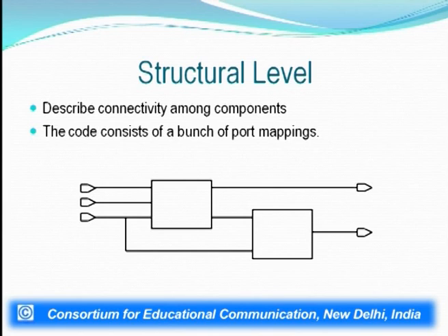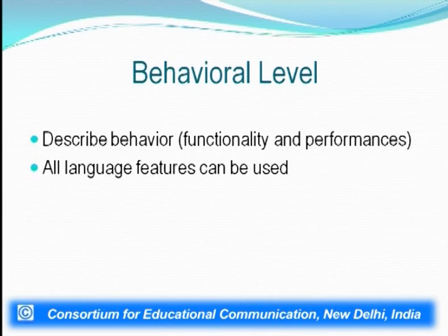For example, talking about a simple full adder, a full adder comprises XOR gates and some AND gates. So a structural level definition would require defining as many XOR gates and as many AND gates as are required to produce the output, and along with that the ports for inputs, that will be the 2 bits to be added and the carry bit, and 2 ports for the output, that is sum and the carry out, have to be defined.